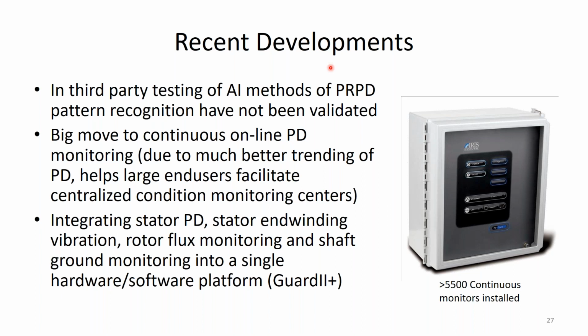The other thing we've been moving towards is integrating stator PD with other types of rotor and stator monitoring systems. Some of you might be familiar with this: not only do we do stator PD, we're not a PD monitoring company, we're a winding monitoring company. So we also do end winding vibration, flux monitoring to detect problems with shorted turns and aging of the rotor insulation, shaft voltage and current, and shaft ground monitoring, both of the voltages and the currents.